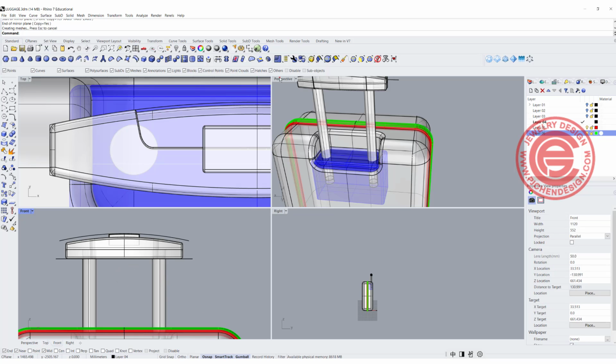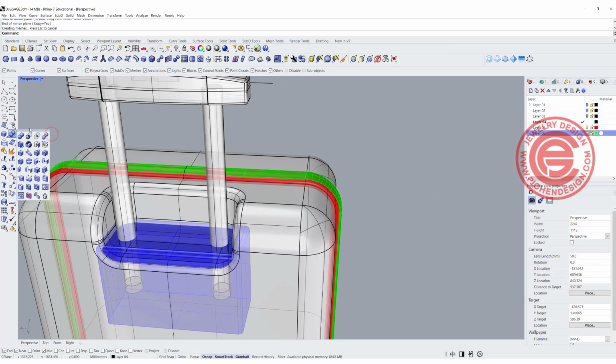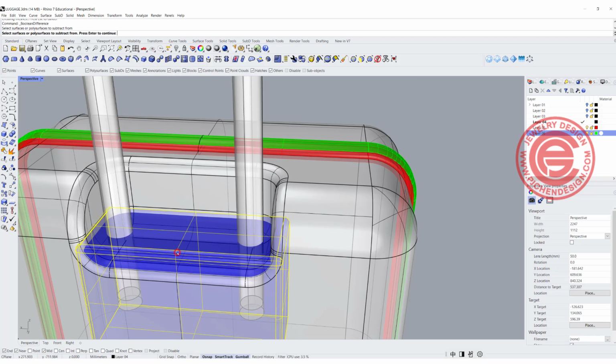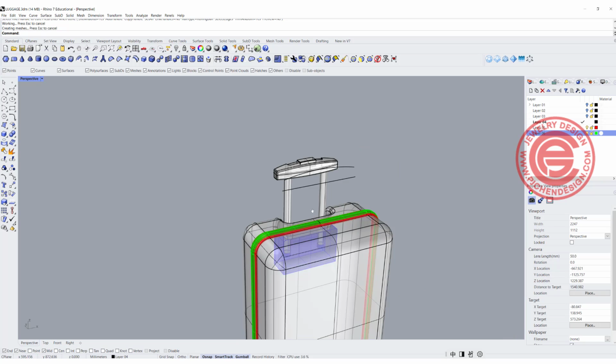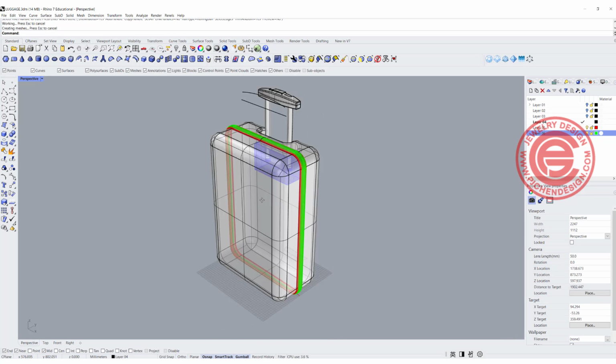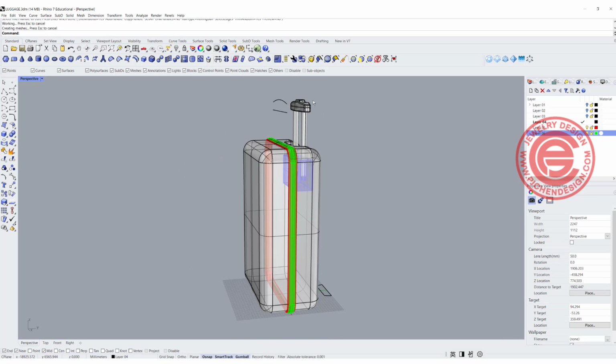And then we're going to do the Boolean difference again. This one out of the bigger cylinder, not the small one, the bigger one. So cut out two holes and do the fillet edges like this. Okay, so now we have the part on the top ready.